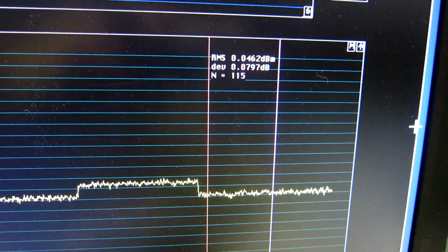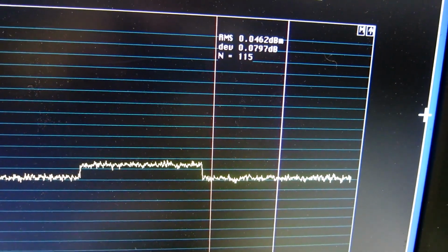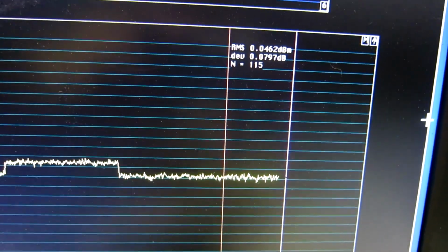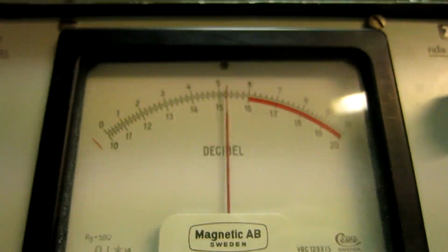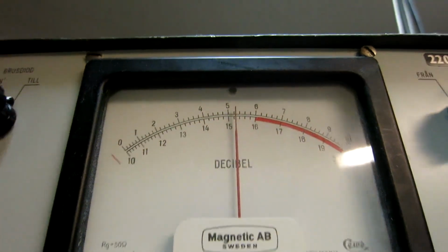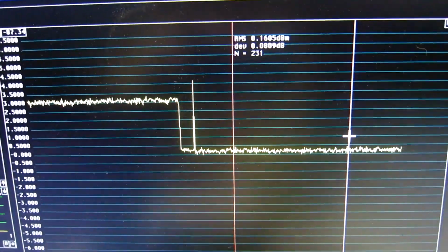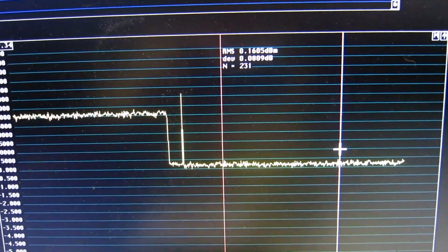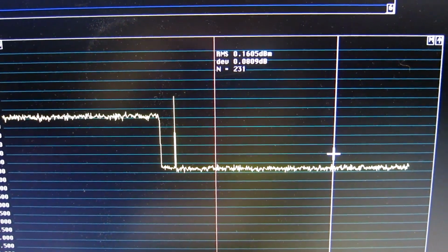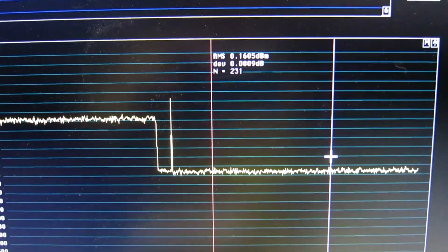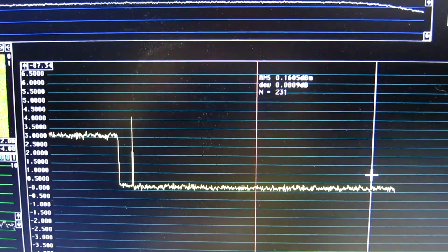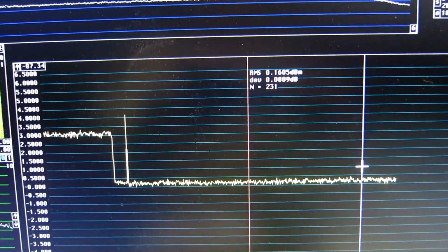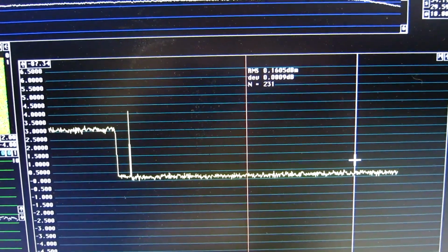This is now the low noise amplifier connected directly to the noise head. And I will check the noise figure. And here I have a 3 dB increment. And that is for a noise figure of 5.3 dB. And now I connect it to the 50 ohm output from the junction FETs of the selective amplifier. Here the noise is 0.16 dB above the system noise at the noise figure of 5.3. So it's a very low excess noise.